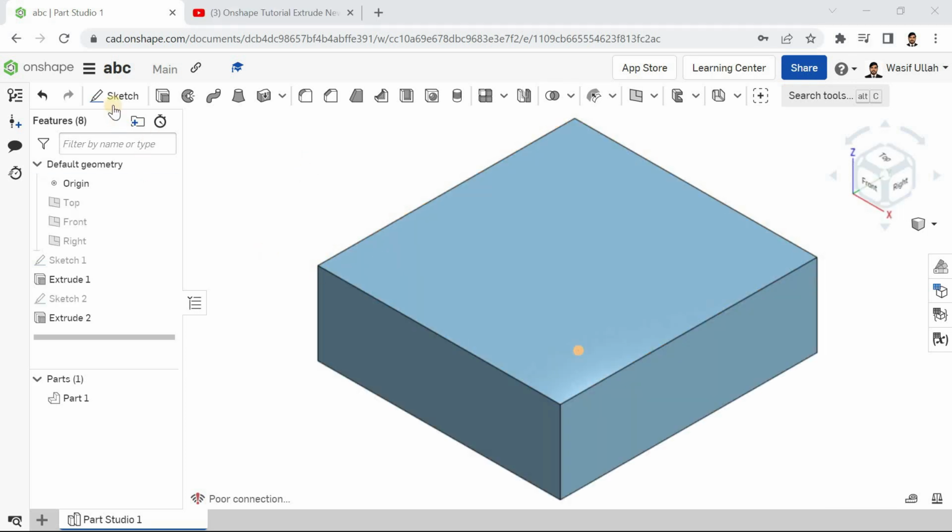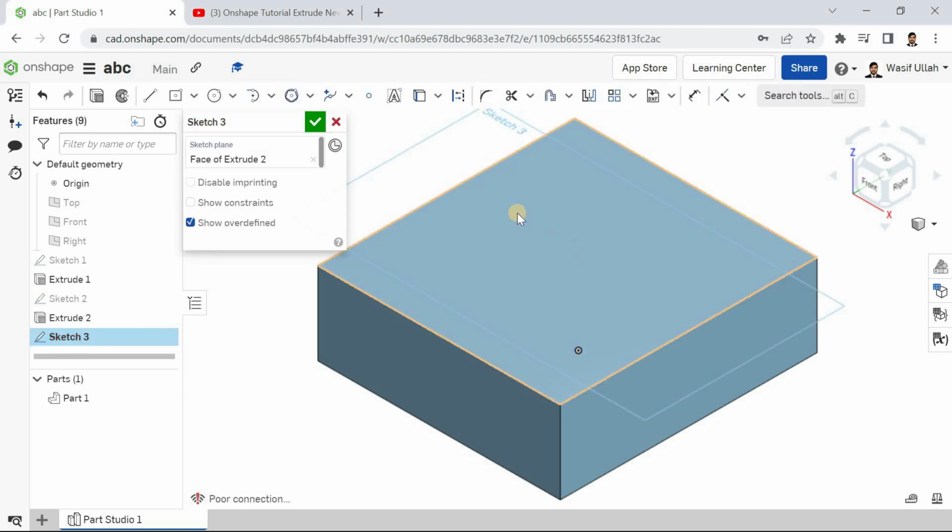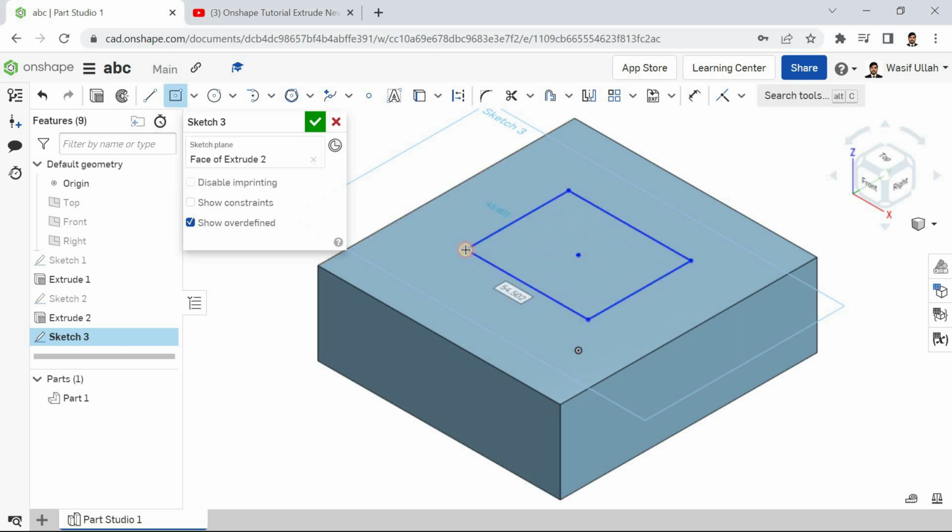Hello and welcome back. Today let's talk about the construction tool or the construction sketches. Sometimes we want to sketch something, but that is not the particular sketch that we want to be extruded, but you can just call it a helping sketch, right? So if, for example, I just want to go for the center point rectangle starting from somewhere here like this. So either you can just extrude this section, press escape, and let me just go for the construction tool, and let me just select this, and this, and go for the construction.